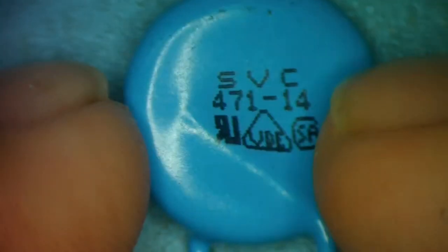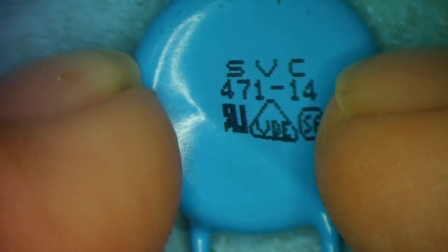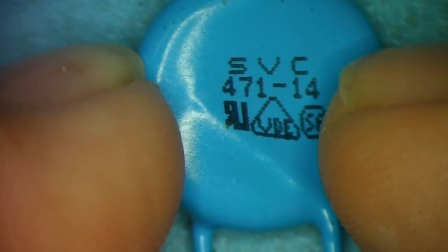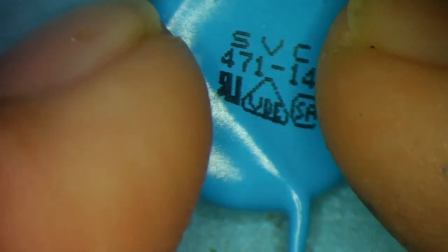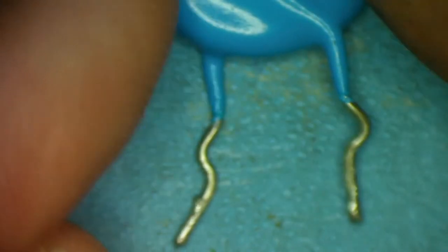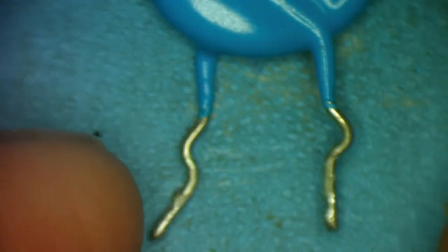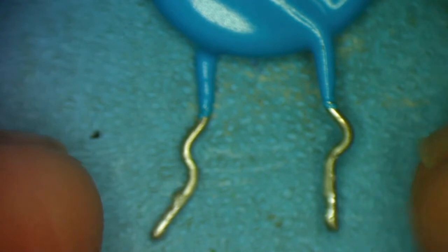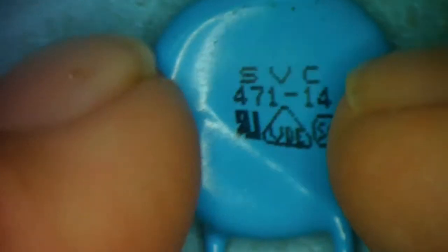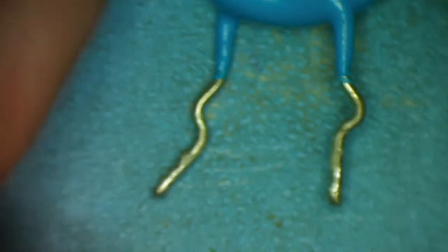Normally this will act as a very, very high resistance, like 1,000,000 ohms, while the voltage across it is below a certain point. So you might have one that's designed, for instance, to have 1,000,000 ohms until the voltage across it reaches 115 volts, yeah? Once it goes above 115 volts, this drops to a very low resistance. And effectively that will short out the 115 volts coming in and blow the fuse, and sometimes blow this up.